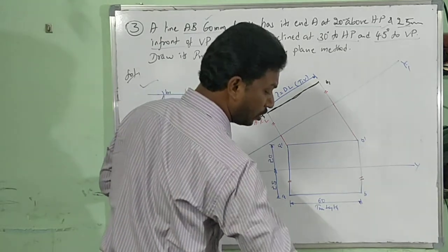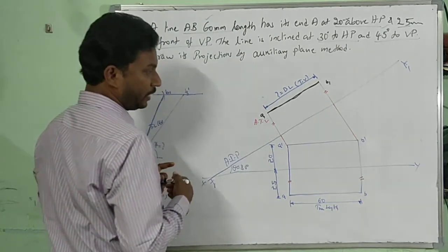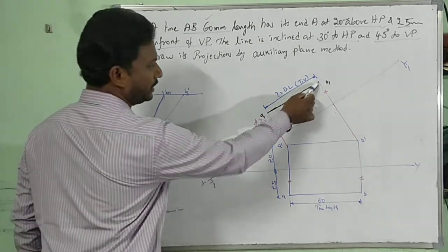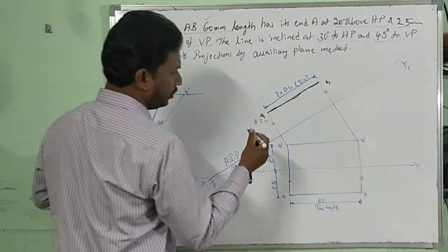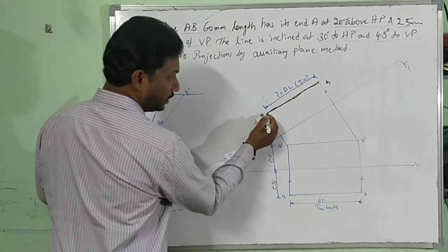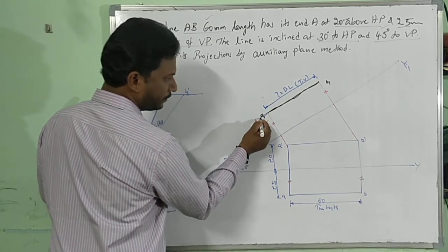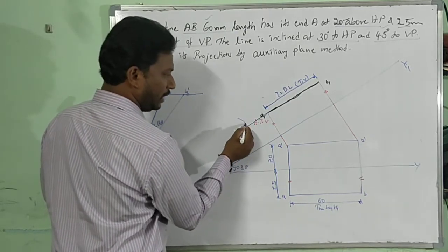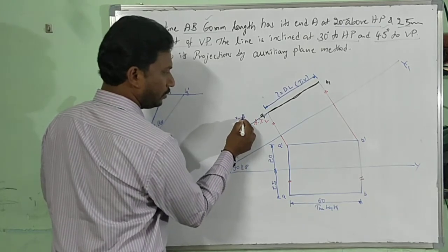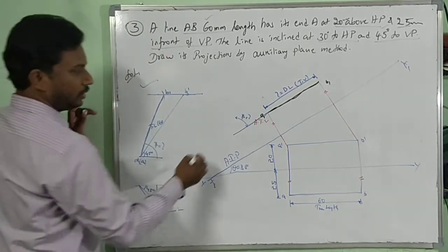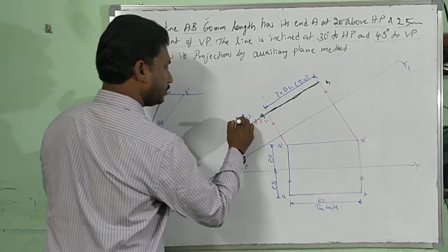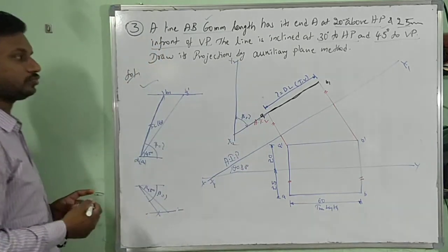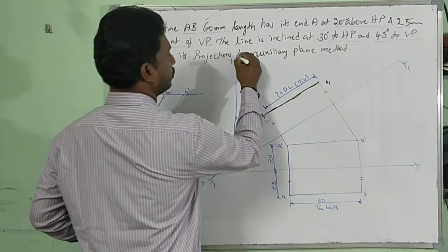Now from here I have to draw a line, right? See, for this I have to draw an angle, but it will be a little bit difficult. So for this line, both are parallel. You can draw anything. Now what I am trying to explain to you is just extend this line. Align your drafter, with an angle of beta, which you have found, right? Try to draw a new line, x2, y2.